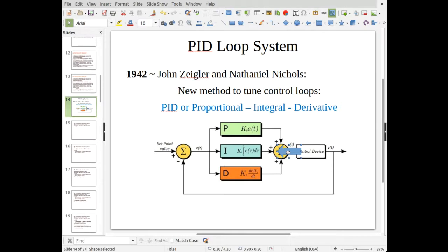And what that's going to do is allow us to push that system. So when the system has a lot of error, the integrator says, here's a bunch of error, next time around I'm going to push it a little bit more because it's not getting up to that steady state value. Then the next time around the loop, I still have error. Maybe it's a little bit smaller because I pushed you harder last time, but I still have error, so I'm going to push you a little bit more.